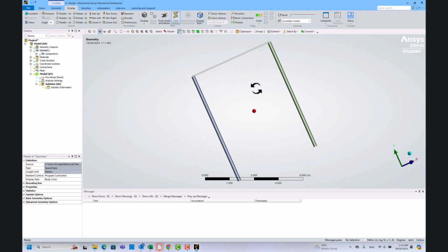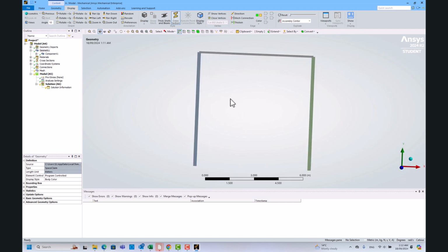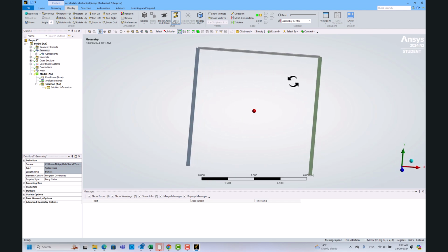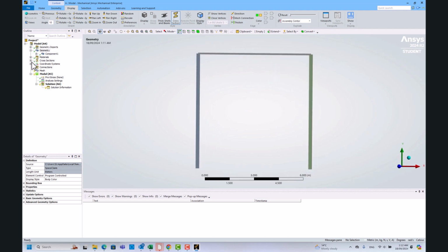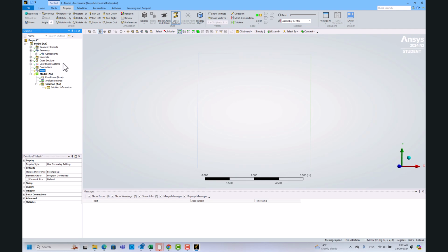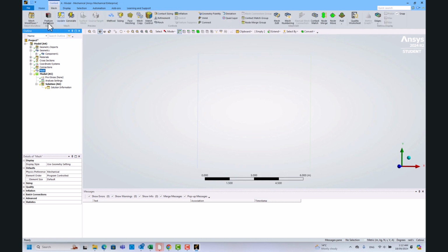So that just shows the beam structures. So the different colors represent the different types of beams. Okay. And then we just need to do the mesh. So for our case, we just use a default mesh. That shouldn't be a big problem. So you can see we have roughly 20 elements on each beam.